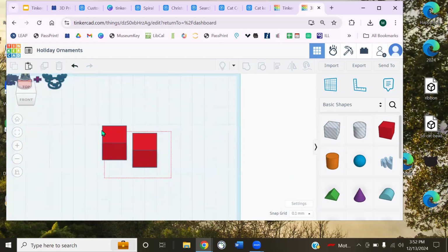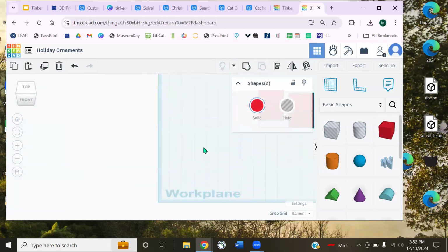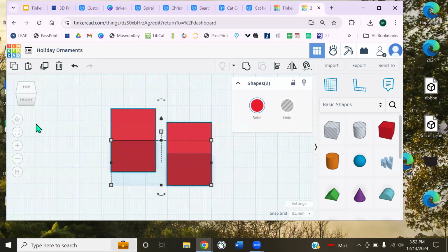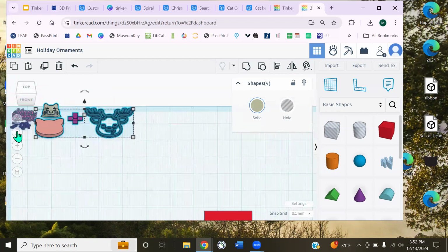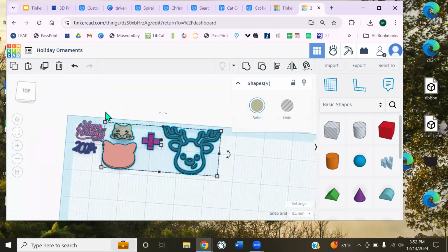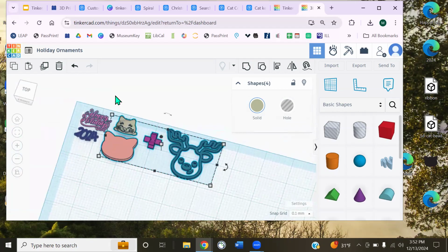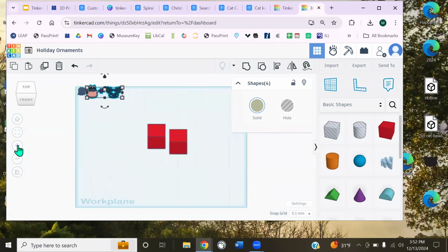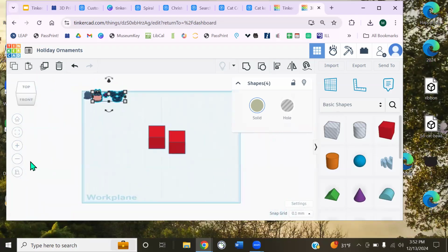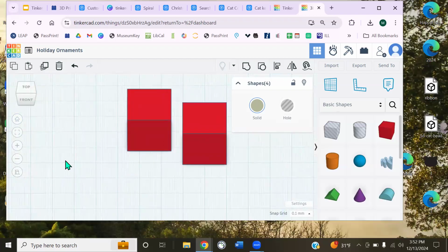So if I left click on these two guys, but I'm not looking at them, and I click on the fit all in view button, it's going to focus in on my selected objects. So if I want to look at these couple things, I'll click fit all in view, and then I'm going to zoom in on those. And any time I'm too zoomed in, I can just click home. It'll zoom me back out and look like that. Plus and minus, obviously, will just zoom us in and out. Same thing as the mouse wheel.